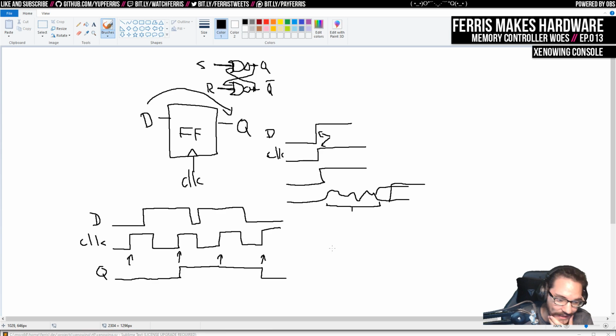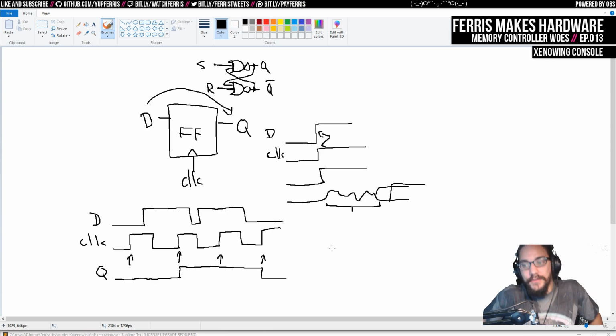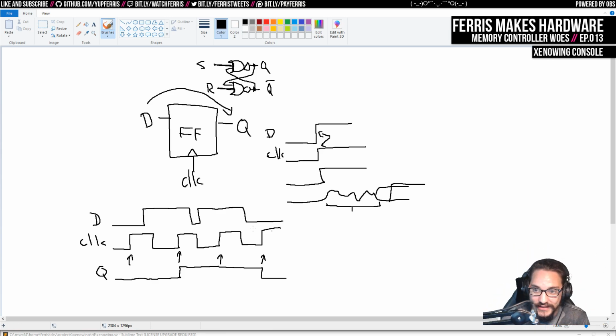But yeah. So the problem with this is that when you have resets, because a lot of the time you also have a reset input, which is often called clear, that this basically overrides this edge. And I should mention, before I talk about clear, that this sort of time for safety around this clock edge, we have what we call a setup time.